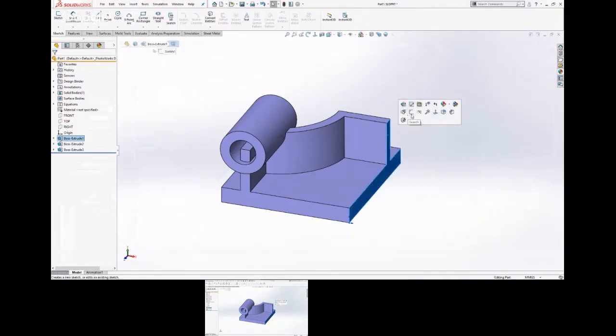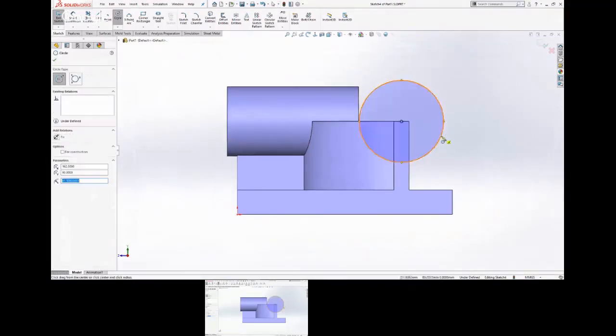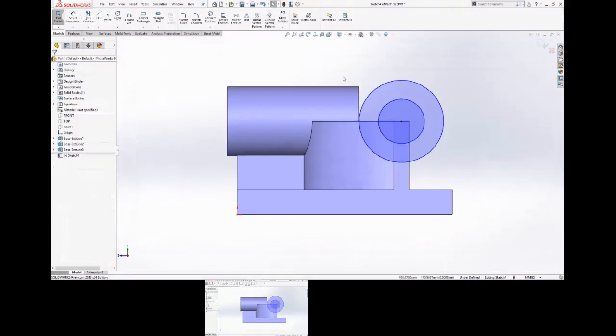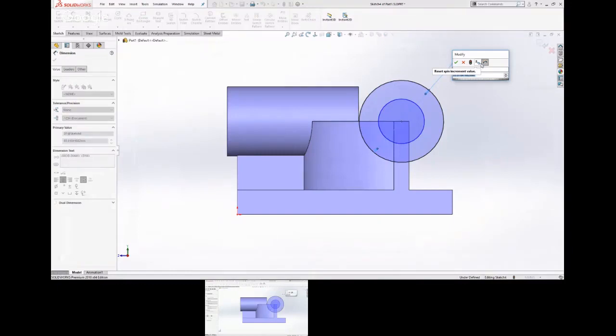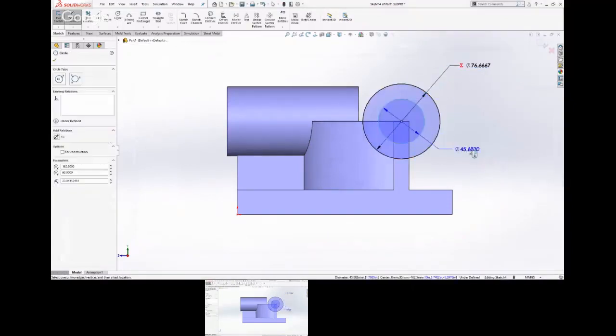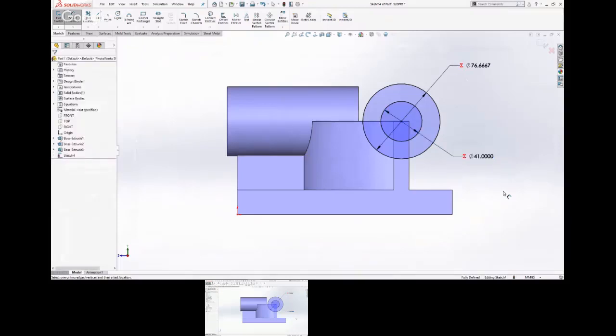All right, so now we've used that variable in 2 different places, in the dimension and then the extrude value. Let's go over here and we'll create the same, or a similar part. This has different dimensions. Again, it's just a couple of circles on that midpoint, and then some dimensions. I like to dimension the outer one first because that's going to be the bigger one, so you don't end up with 2 lines on top of each other, and it happens a lot. Then you have to zoom in, and it just makes it a little bit more complicated. So the outer diameter on this one is Y, so equals Y. If I hit enter twice, sometimes it'll work, sometimes it doesn't. And then the smaller inner diameter is E. So that time it worked. Okay, and there's that part.